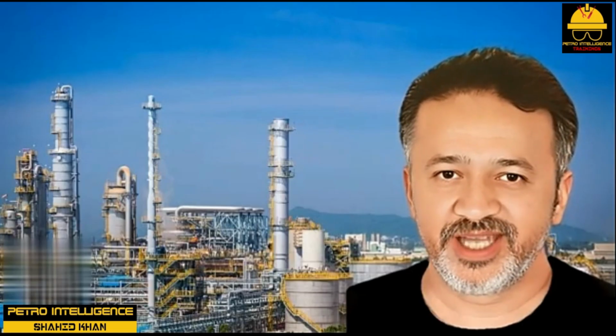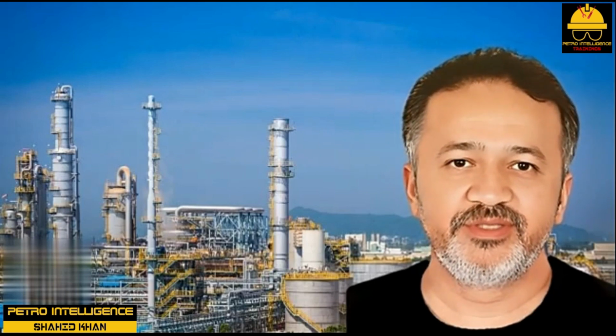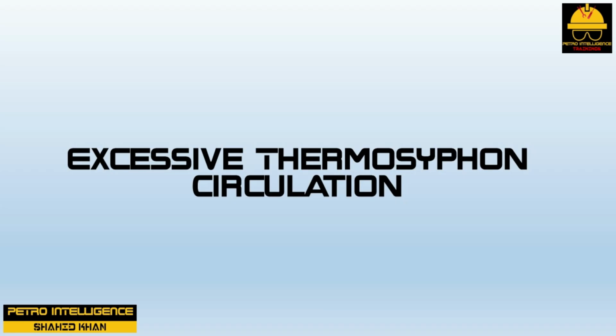The superfractionation stage. A once-through thermosiphon reboiler not only functions as the bottom theoretical stage of a tower, but it also functions as if it is a superfractionation stage. This means that it is more important than any individual tray in the tower. This is especially true with a multi-component tower bottoms product. We will discuss this concept of superfractionation in an upcoming video.